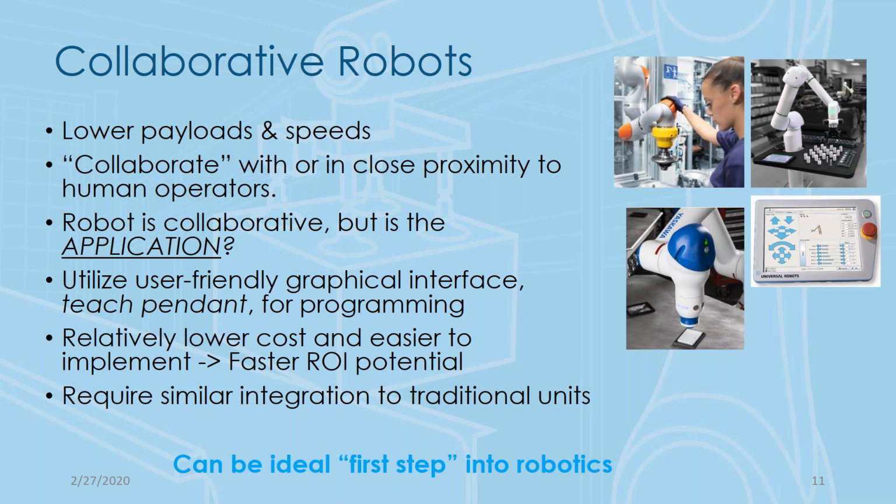We're looking at an application once where the client was considering picking and placing sheet metal. They had 1 foot square pieces of sheet metal they were going to move around with a collaborative robot. And so the issue is the very sharp edges, and you do have to consider what you are moving around, because that makes all the difference in the world. You definitely didn't want an operator close by there when the robot's swinging around that piece of sheet metal. So that is key in whether or not the application is actually one that lends itself to a collaborative robot. Yeah, absolutely. Thanks, Raminder.